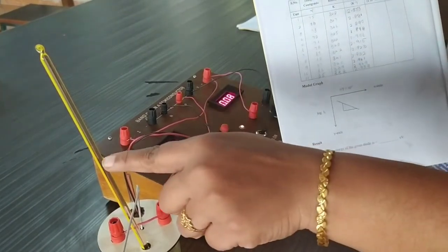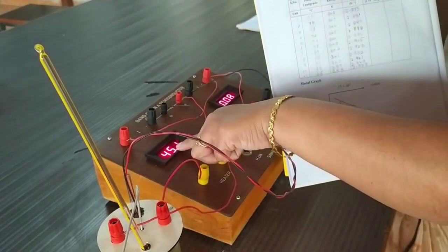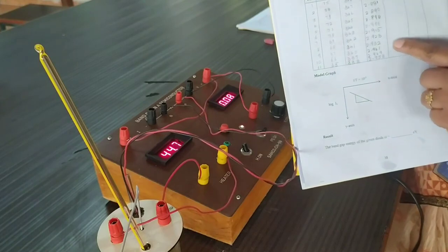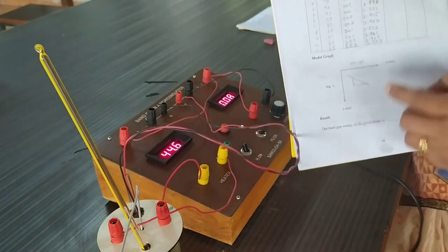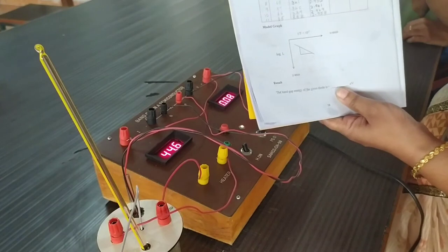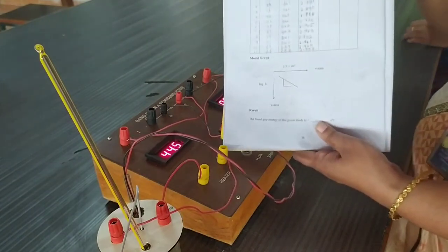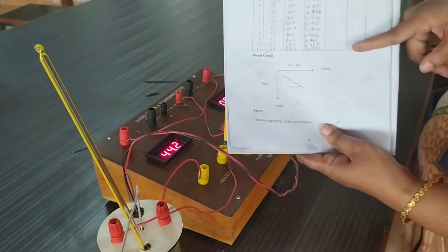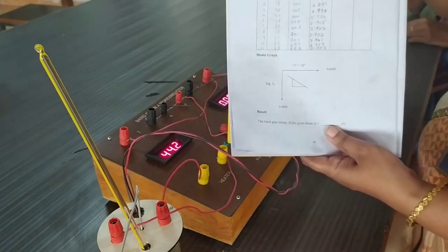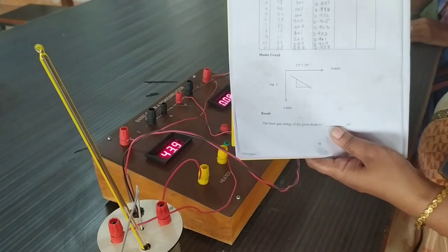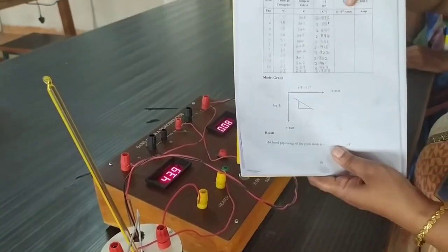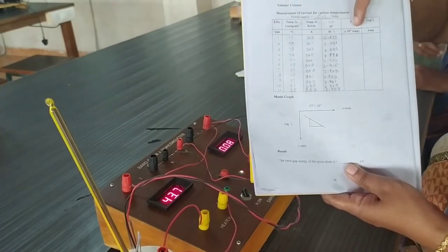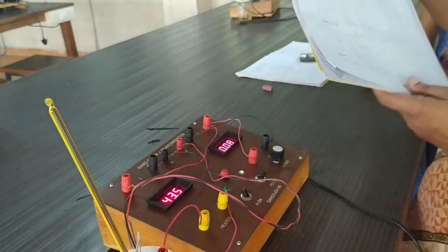Now from 75 degrees I am going to note down the current in the ammeter. I am going to note that reading here. Follow? Okay. So this is how you have to plot the values. You have to record the data that you observe. For each degree fall of temperature, I am going to note down the current, because using the technique of reverse saturation current, we are going to find out the band gap of the semiconductor. So shall we do? Yes.